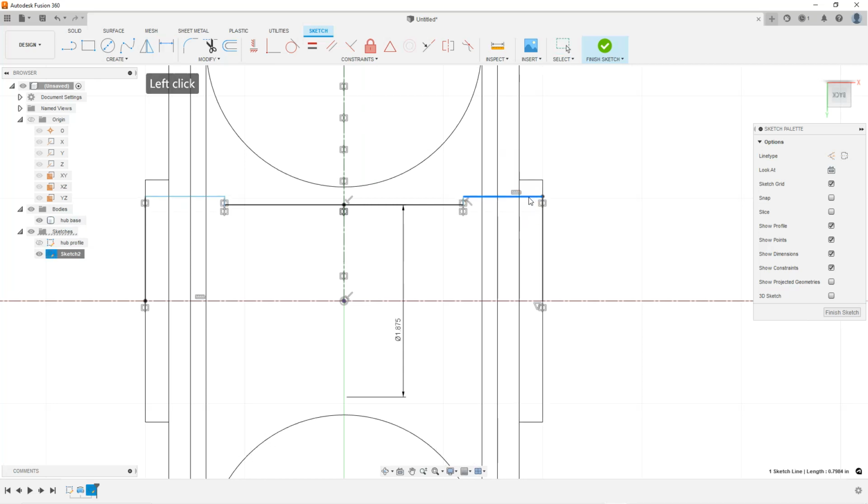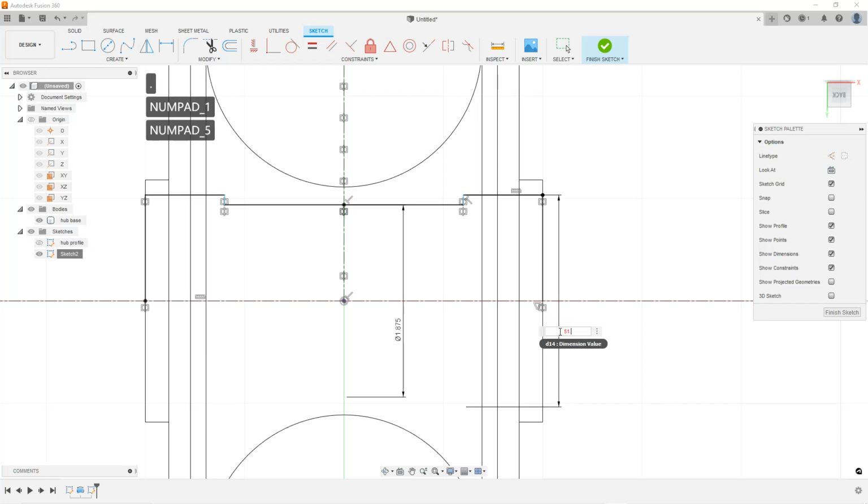Okay, and then our bearing bore, I'm going to use 52 millimeter bearings for this thing, so let's just call this a 52. Well, actually, to be correct, let's do a 51.95 millimeter, because that would give us a press fit for that bearing. And I know that the depth of this bearing bore is going to have room for the bearing and then room for the seal. And I know that my bearing is a 15 millimeter width, so I'm going to put in 15 millimeters. And then I also know my seal is a 7 millimeter seal, so I can do that.